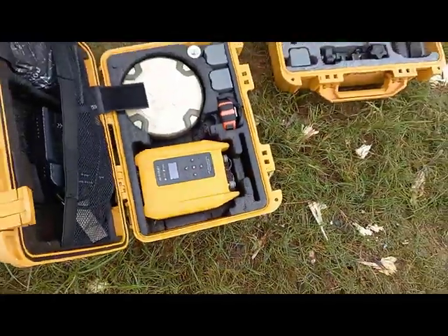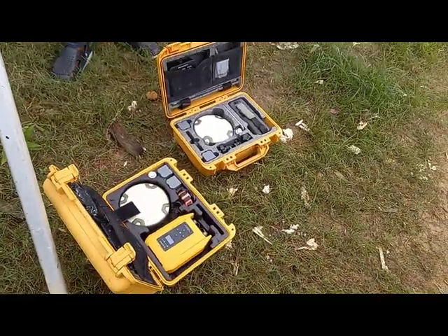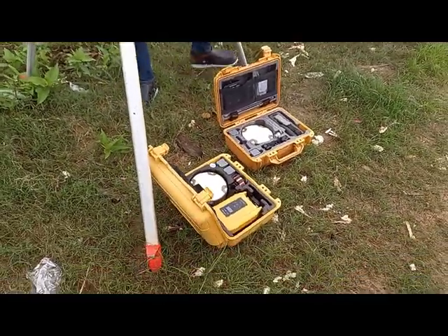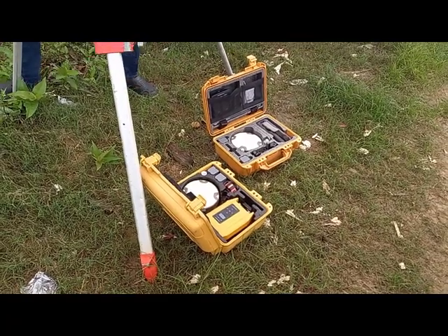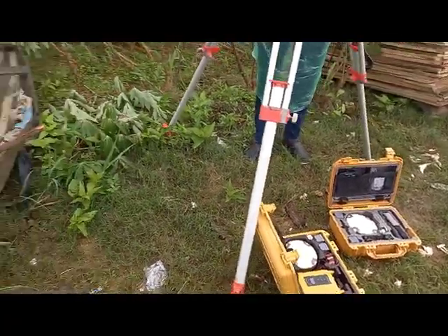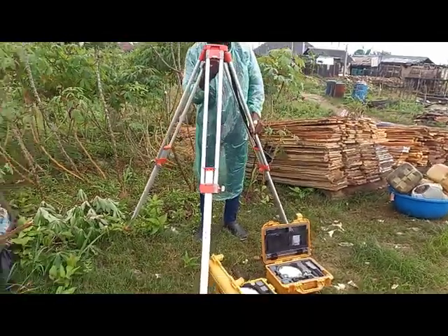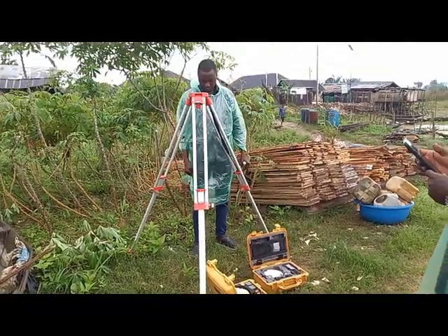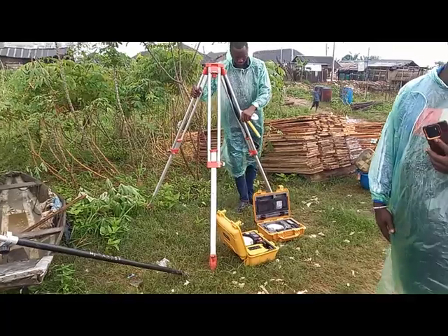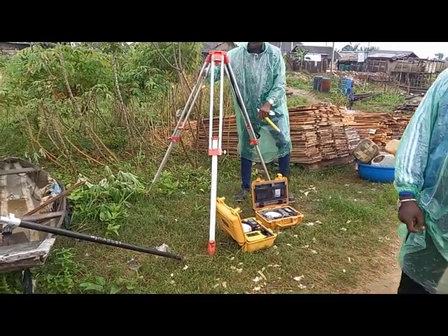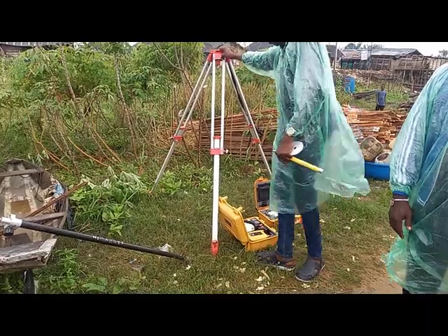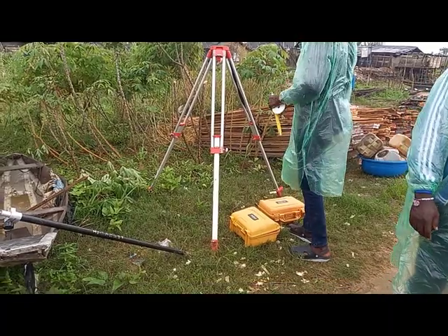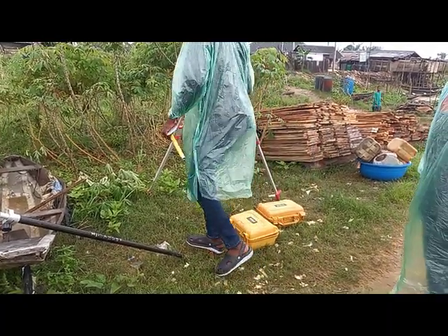So basically, for you to actually use the differential GPS, what you're going to do is set up the base device. You set up the base GPS in one location. You then calibrate the rover according to the base. So the base would have already picked up data as to the satellite and the elevation at that point. So that base GPS is now going to be calibrated with the rover GPS. So the elevation of that base GPS, the coordinates, is going to be calibrated with the rover.